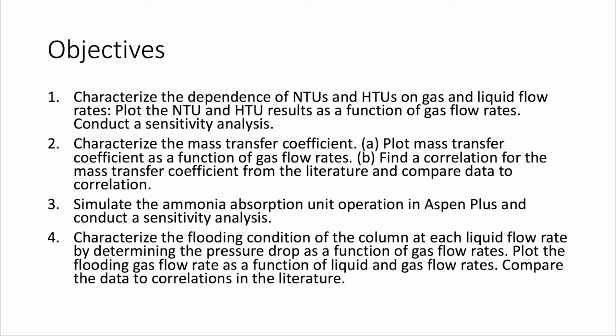For the third objective, the absorption unit was simulated using Aspen Plus software. Finally, for the fourth objective, the flooding condition of the column was characterized by measuring the pressure drop at different air and liquid flow rates.